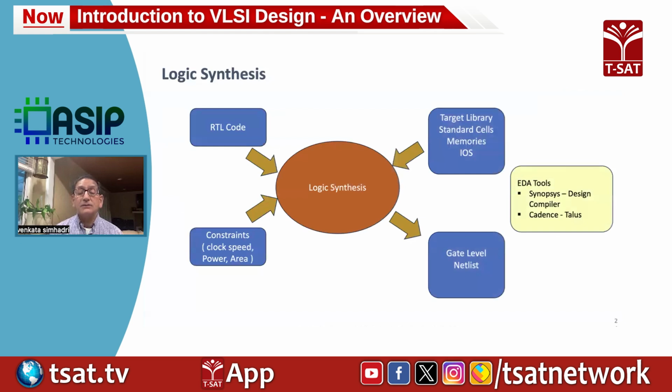So this is how the synthesis step works. Logic synthesis is the EDA tool, and the inputs you give to the tool are the RTL code you have developed and verified. Then you also create a constraints file and give it to the tool as an input.